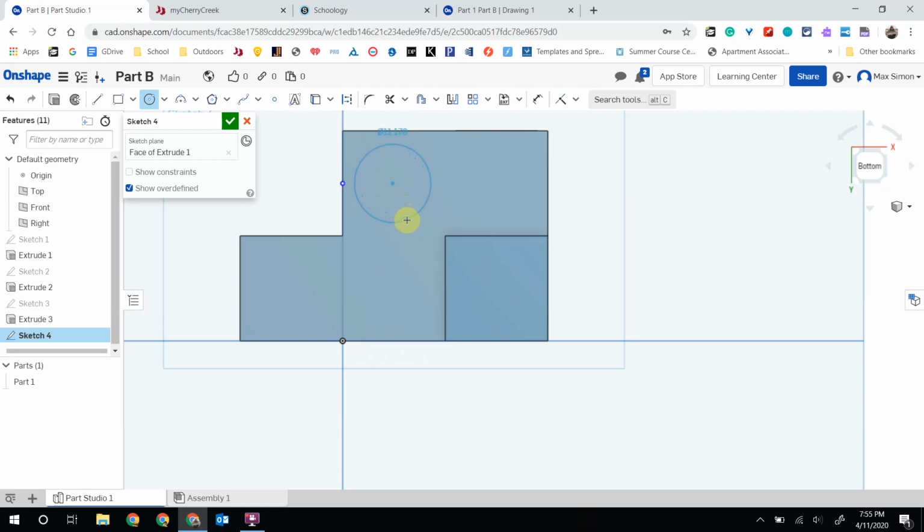So we're going to draw that circle out here. So we know this one's already there in the middle. So we need to use our dimension tool anyway to take this and lock that in at 12. And then we need to smart dimension. We've already told it to lock to the center here, right? It's 7.5 because 7.5 is half of 15, which is this depth here.